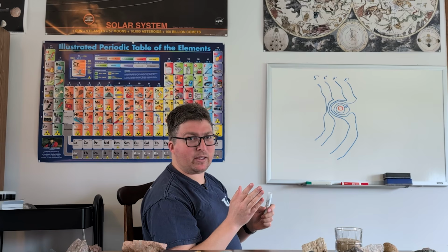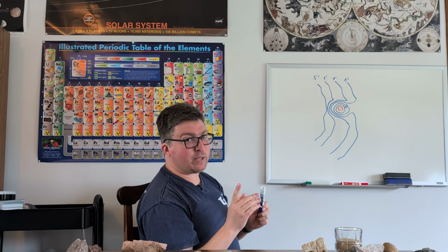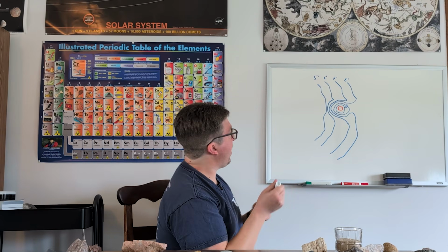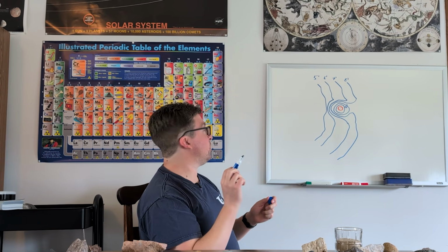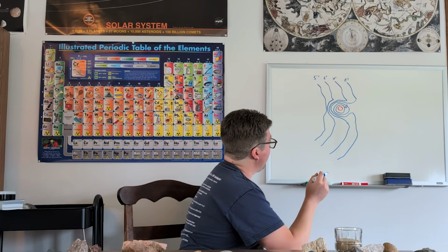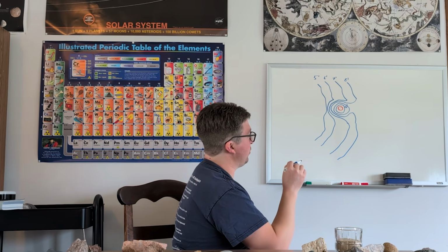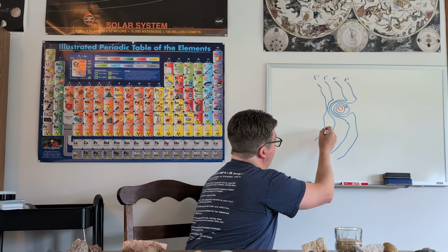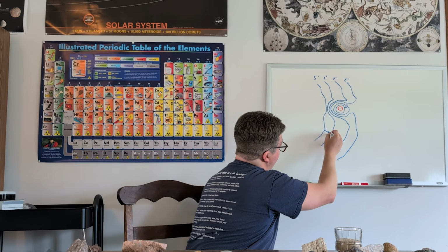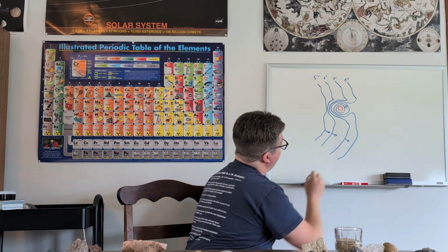Now, how do we understand the direction of flow of groundwater? Generally speaking, not always the case, but again, we're not getting into weird cases here. Water flows at a right angle to the topographic lines. So it wants to flow downhill, so to speak. It's gravitationally driven in almost all cases. And so your direction of flow for the water is going to be here, like so.